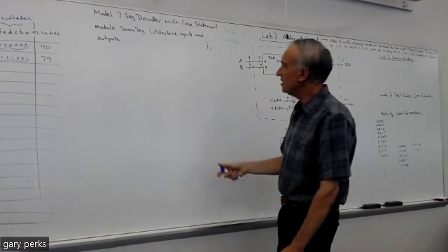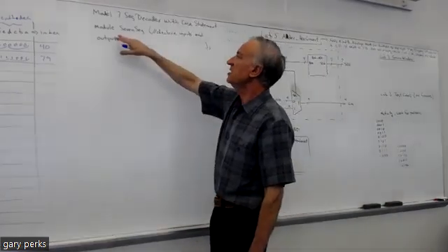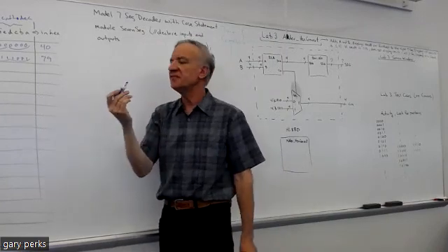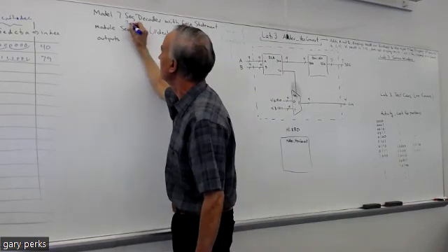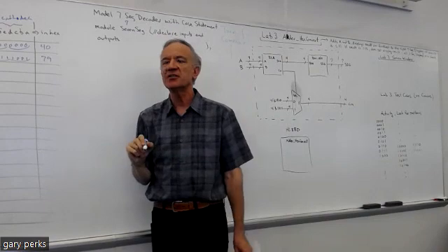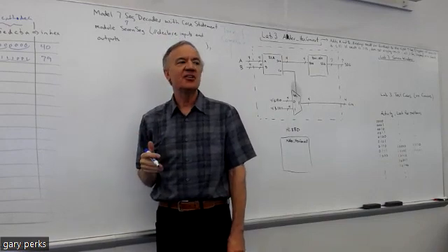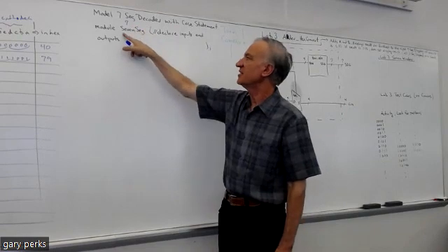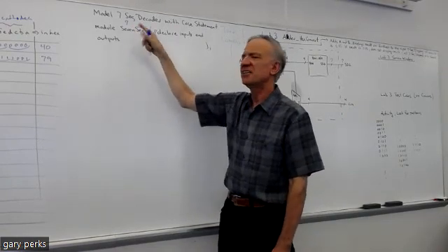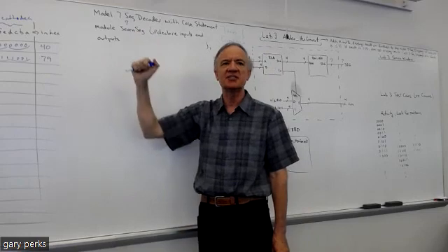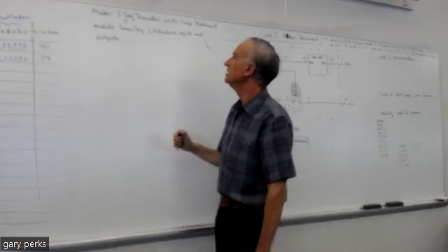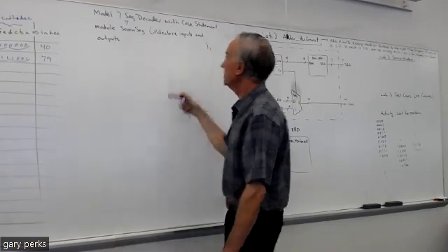So anyway, like any module, you give it a name. Now, I'm not positive, but I think if you start a file name with a number in Verilog, SystemVerilog, it doesn't like it. So don't do 7seg like that. You've got to spell it out. I don't think it likes names with numbers at the very beginning. I think you put numbers later on, but not at the very beginning. So that's why I have it spelled out here.